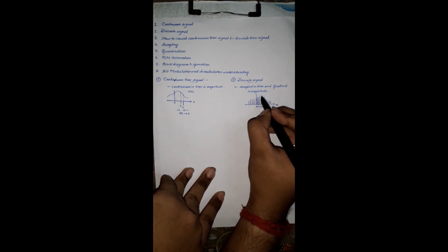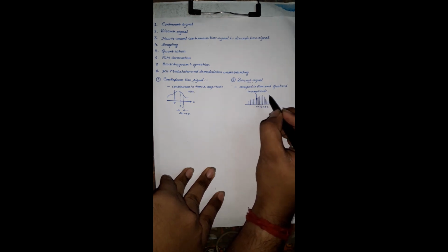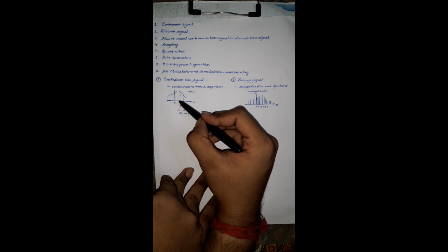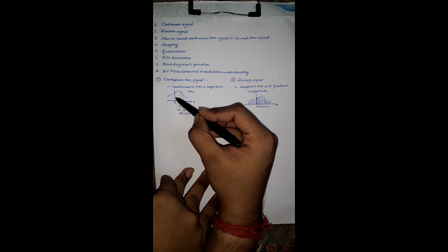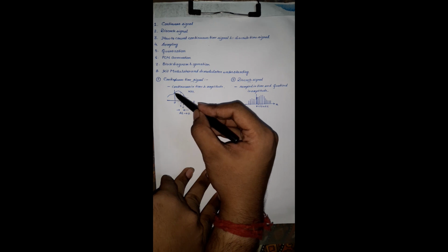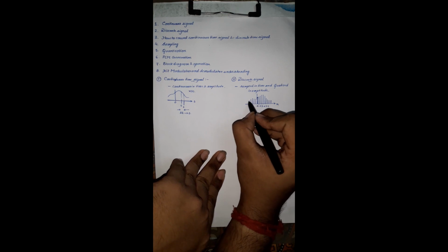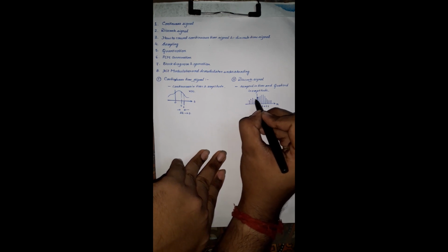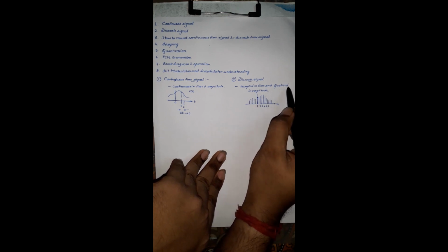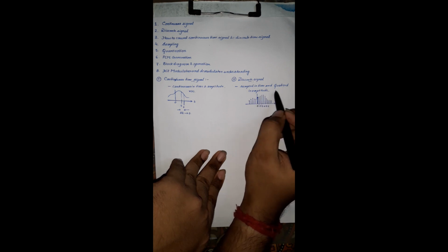And not only that, we will find a finite value. That means for the 0th instant the signal has a particular value, but for the previous case at the 0th instant, we can't say that this signal has a particular value because its value is continuously changing. But here the value is discretized. As we are finding each and every instant's value, these values are called the quantized values.